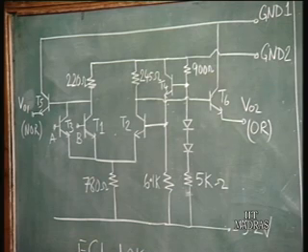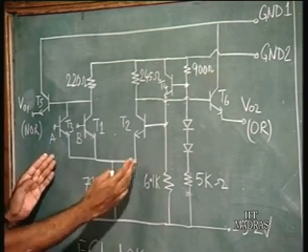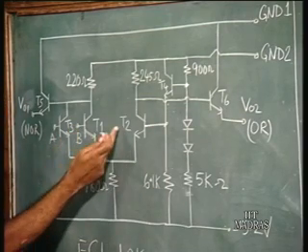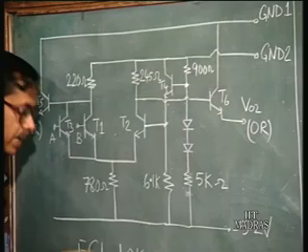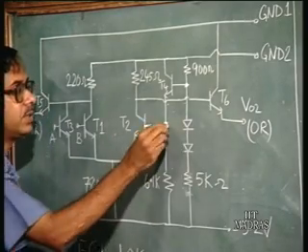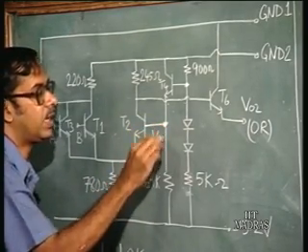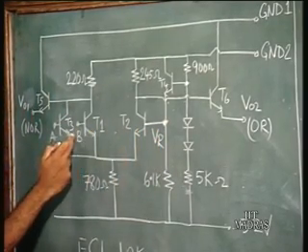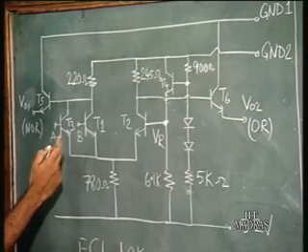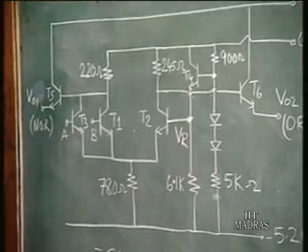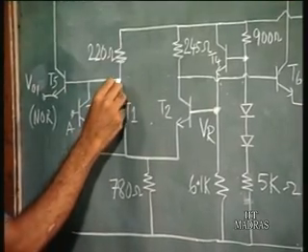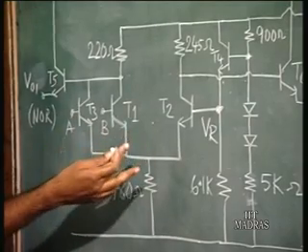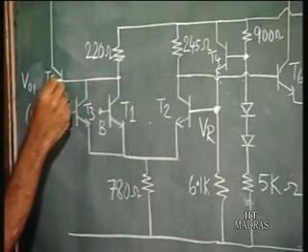As you see here, this part of the circuit is the emitter coupled configuration. You have the transistor T2 on one side, and at the base of that you have the reference voltage. This is basically VR, the reference voltage. T1 and T3 are the transistors where the inputs are applied. And from the collectors of these transistors, you have the emitter followers.